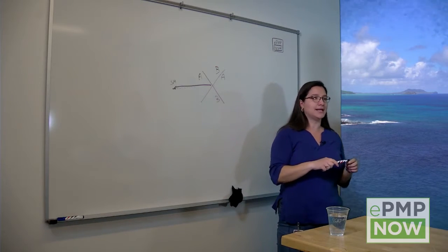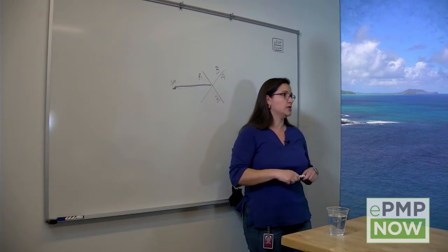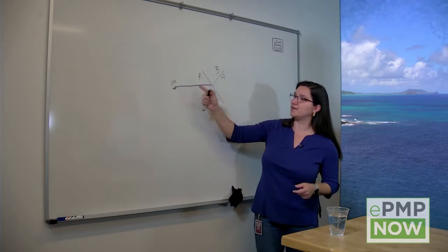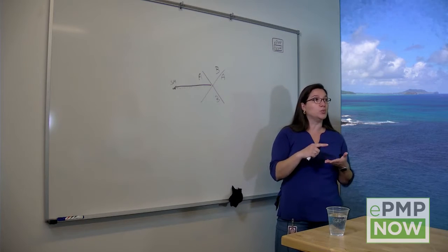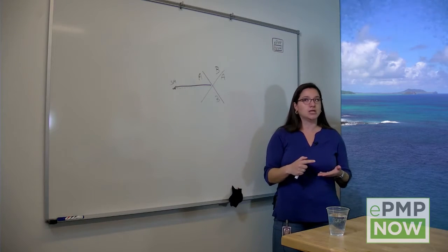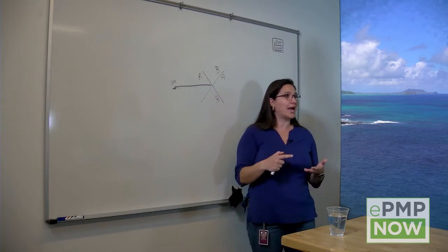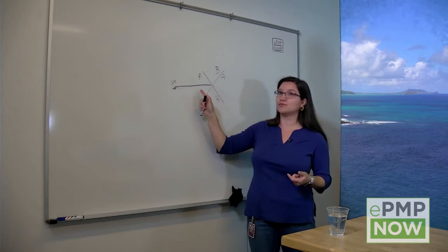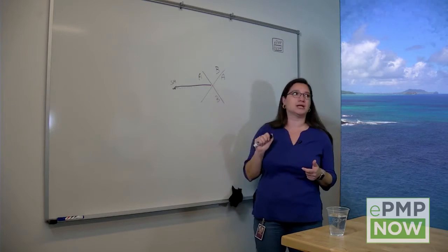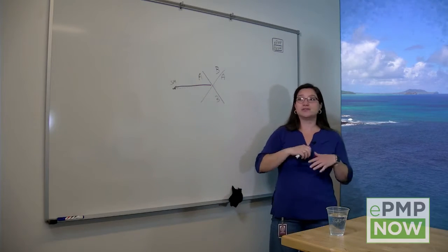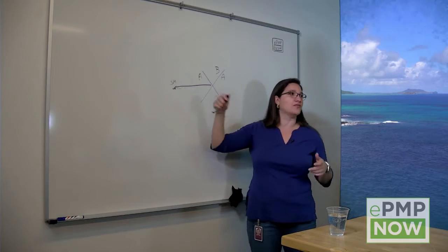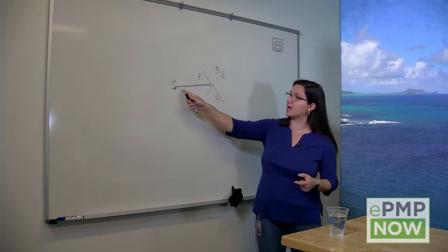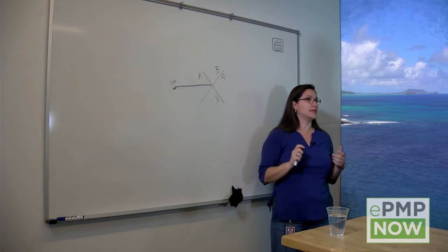Now let's assume the antenna has a poor front to back ratio, something in the 20 dB. What happens? The interfering signal is only 20 dB weaker than your desired signal. So this prevents you from using a high modulation at the subscriber in this downlink direction, just because of your own, if you wish, interfering signal coming from the other sector. This is regardless of the distance of any other interfering signal you may have in the area. Just the signal coming from the back of this antenna would prevent you from using a higher modulation.